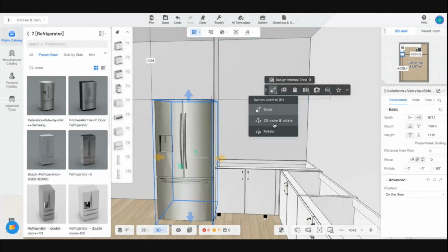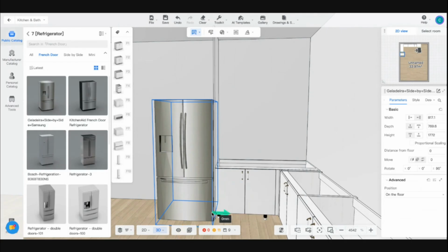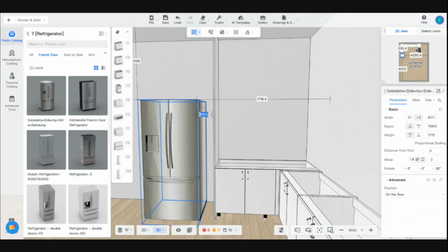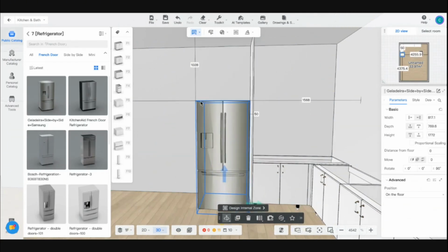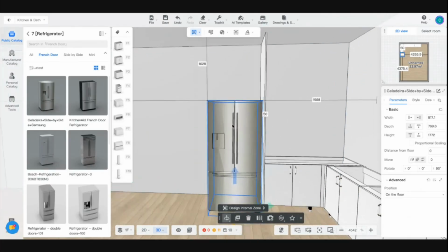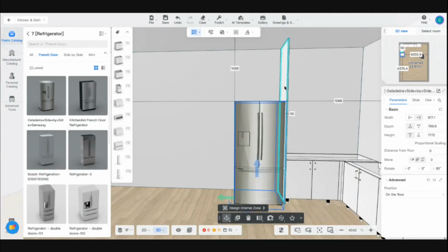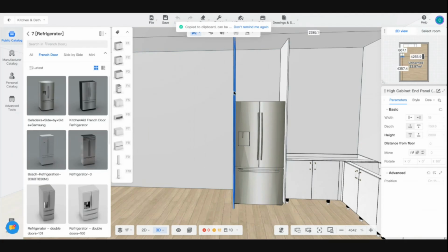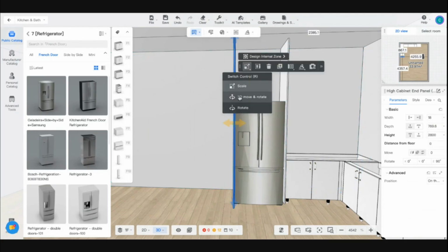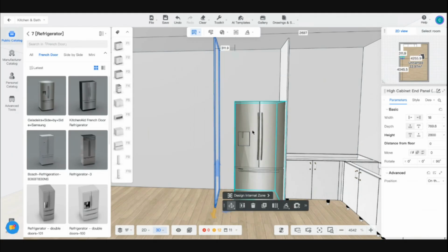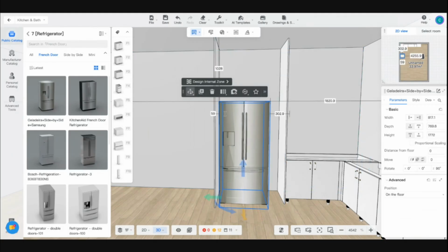I'm going to change this to the rotate movement. So change it here. I'm going to make the gap 50, so like 5 centimeters between the gap. And another part, I will copy this tall cabinet to this part. And then I'm going to change it and move it, like also 50. Sorry.